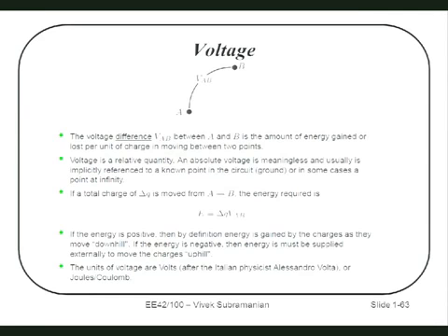So what is the point of the ground connection to the box? The point of the ground connection to the box is to give a low resistance such that if by mistake the live happens to touch the toaster, it guarantees that it'll have a lower resistance path to ground than you would. That's the idea.